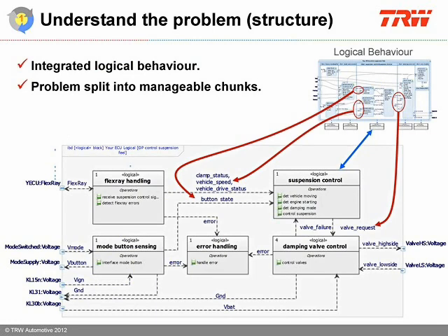Having identified the behavior and some logical blocks, we need to ensure that the ECU function integrates into the overall logical architecture. To do this, we allocate the behavior to the logical blocks and define the interfaces between them. Each activity is realized as an operation of a logical block. The flows between the activities represent the input and output parameters of these operations. Where a flow on the activity diagram crosses a swim lane boundary, it indicates a flow between the logical blocks that represent the swim lanes.